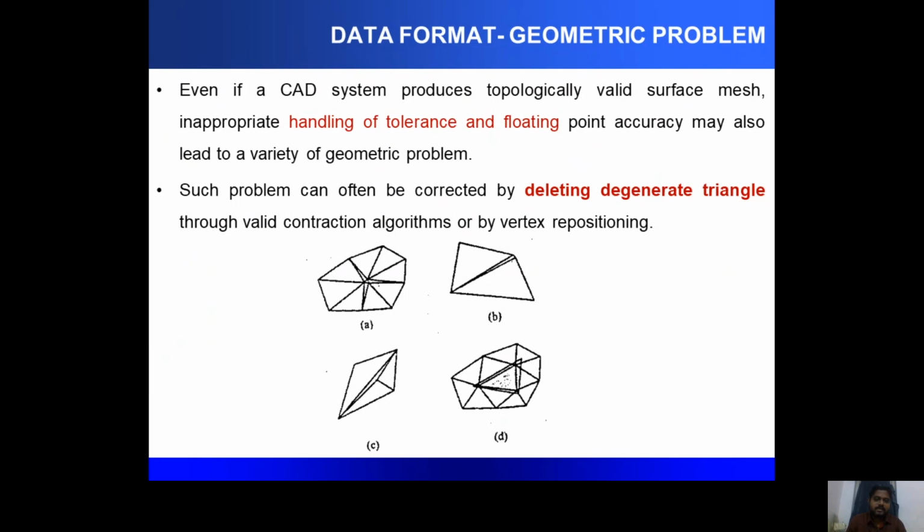If more than 3 decimals are not captured, or if after 3 decimals the value differs from one edge to another edge, you may not get the same value. So this accumulation of geometry value errors leads to unconnected triangles, and this will also lead to errors. This problem happens because of decimal value error for each triangle length.